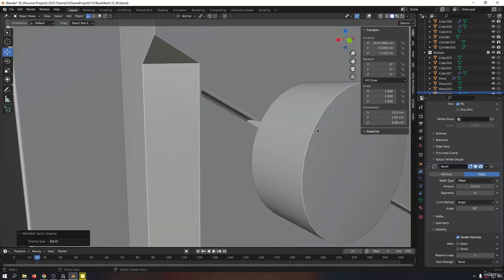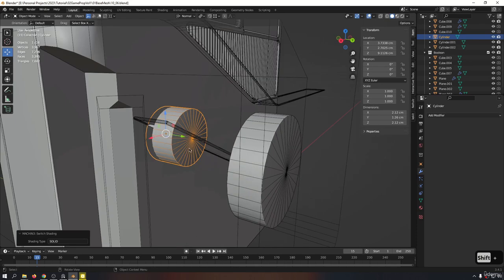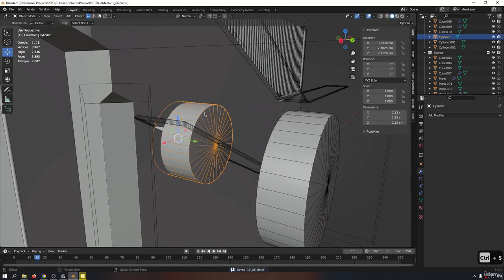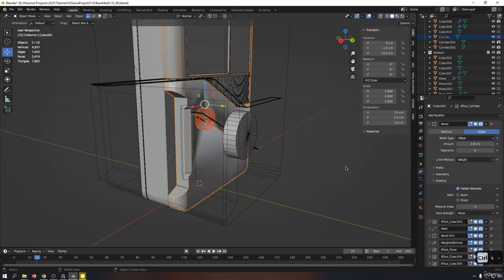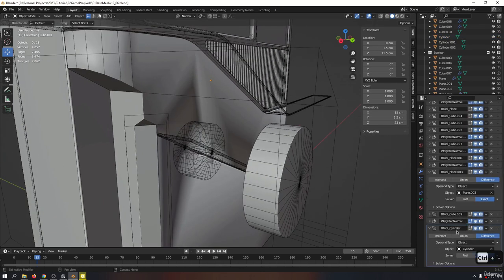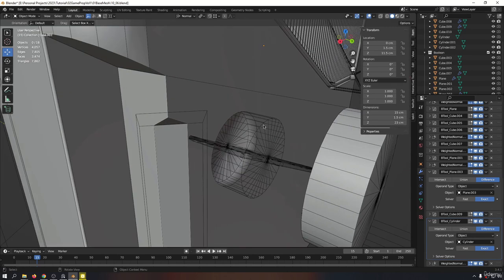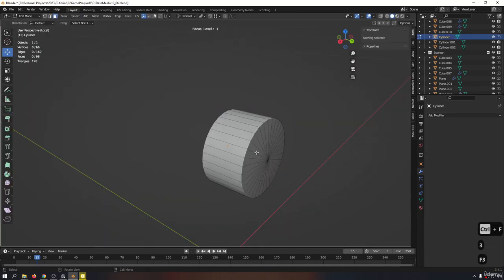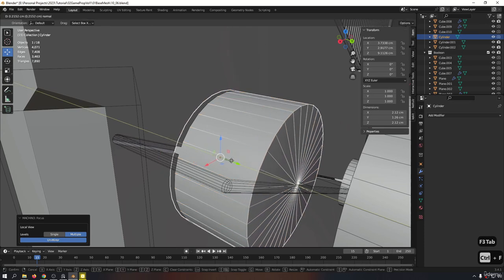So now the next thing is cutting these lines or cutting these circles in the detail. So now I'm going to take this cylinder and take the front panel, Control minus, and looks like again I need to bring up the weighted normals. Always let the weighted normals be the last one so that it calculates the normals a lot better. Okay, now let's hit F3 on this to see what is going on there. Let's drag it out a bit.